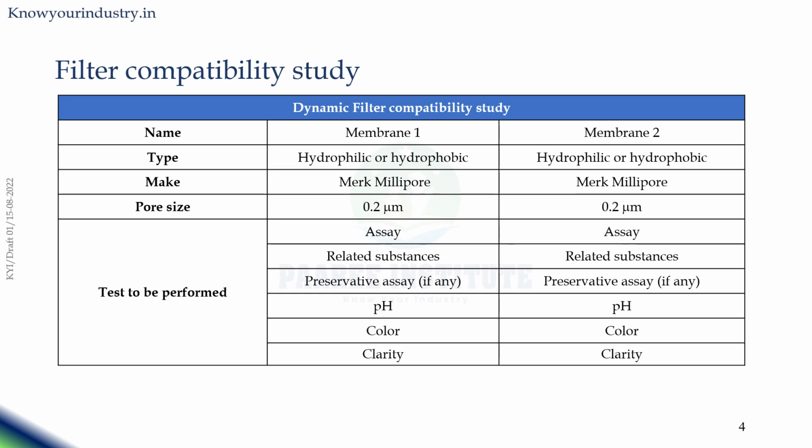Here we have presented a few filter membranes, hydrophilic and hydrophobic membranes of any vendor. Maybe you can select polyvinylidene fluoride, polyether sulfone, nylon, or cellulose. There are multiple filters available. Using these, you can perform this study either by soaking the solutions into it or by passing the solutions and collecting samples at predetermined intervals.